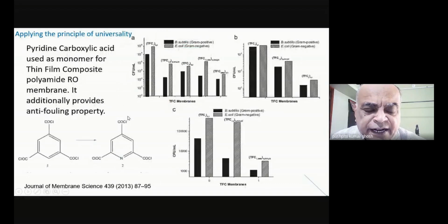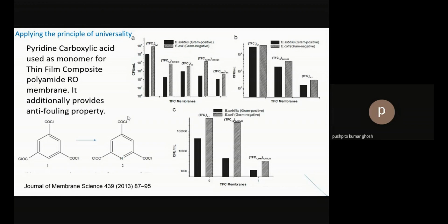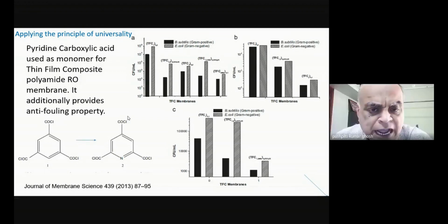One of the problems which we were aware of is that most membranes tend to foul up, and that's a huge problem. They work very well for a few months. After that, their performance steadily keeps deteriorating, and you'll find that it is because of some slimy bacterial layer or some inorganics and things like that which have gone into the membrane, and that's how they lose their efficacy.